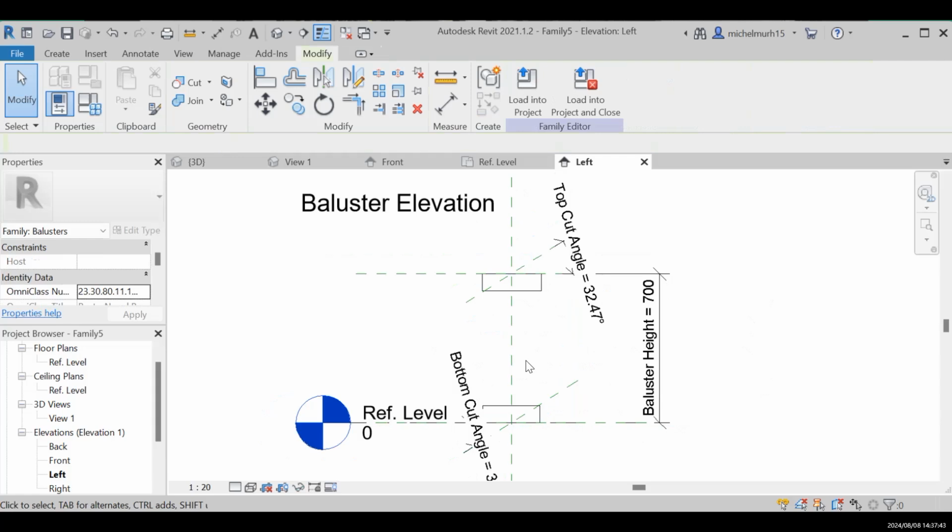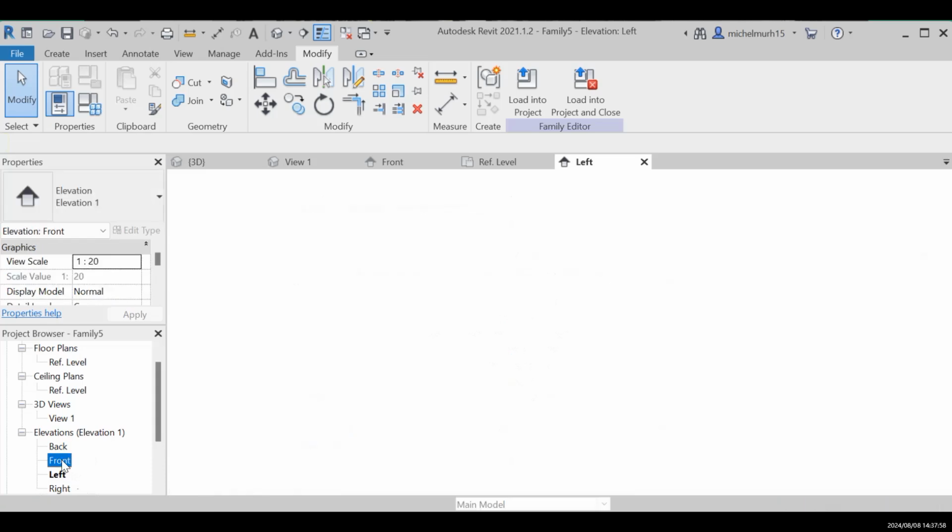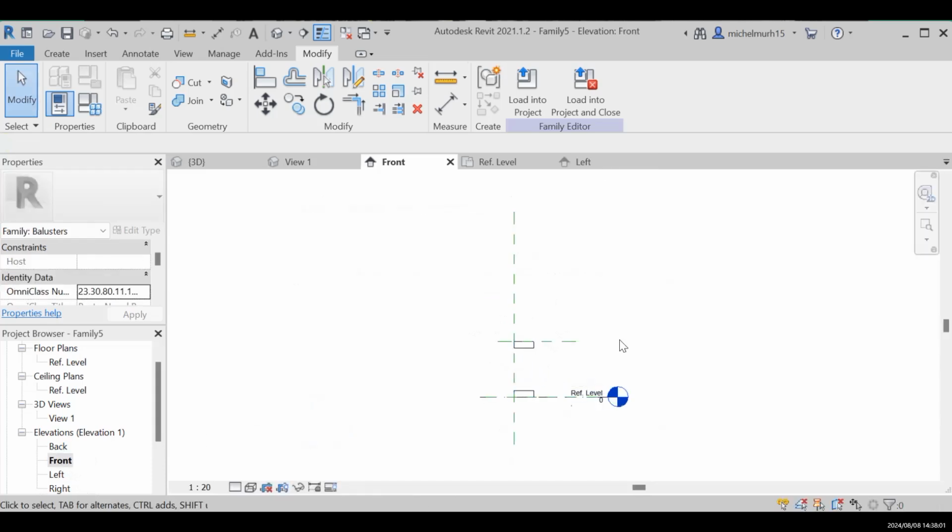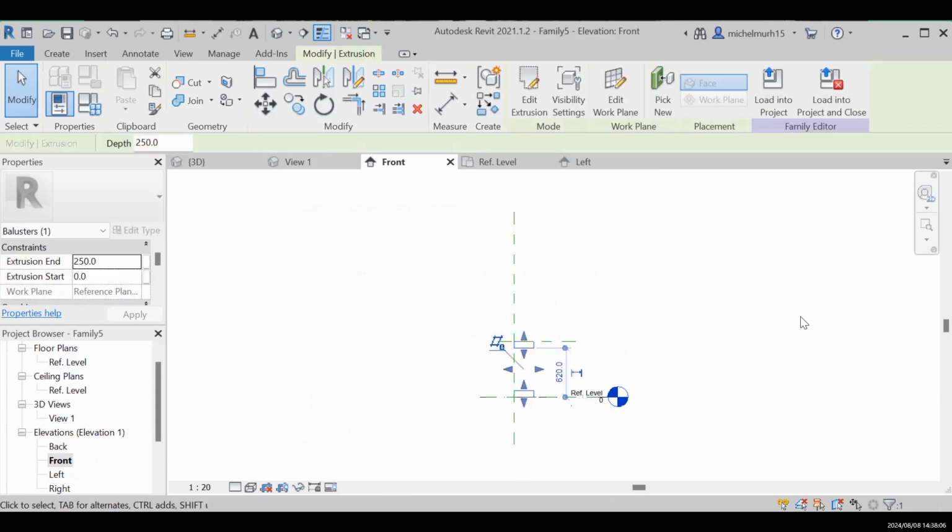So what I'm going to do now, since I finished designing the head of my baluster, I need to start sketching the view of my baluster. First of all, you have to make sure that the front view is also aligned properly in the middle, in this axis here. Just click on one here and then you can modify it. The endpoint should be 60, and the start one can be the reverse of 60, which is minus 60. So it means that they're aligned in the middle, right?